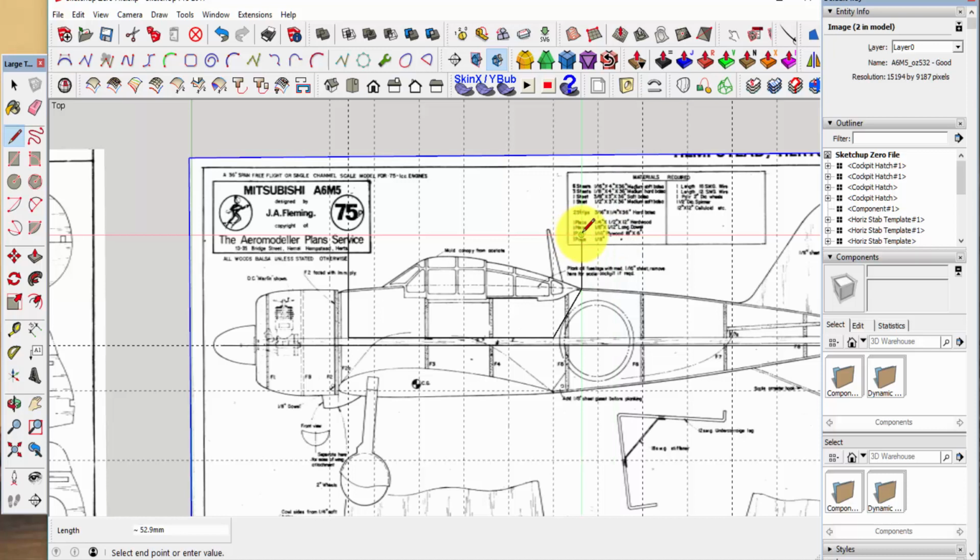Now, we're going to do just, of course, the opposite of what we did for the saddle. We need the template to come this way. So now we'll take the line tool again. We'll bring it back to a known former position right there, so that we'll have a known vertical line to align it with, and we'll come down. It doesn't matter where, really. This is just going to be taped to the fuselage along here to make it nice and steady. We'll put it there, and we'll come up forward, and we can use F1 up forward now. So let's do that.